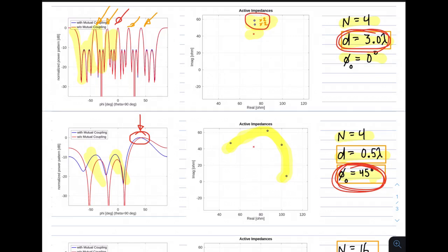Not just for this one pointing, but if you wanted to do a good impedance match for all possible pointings in the H-plane, you see now that you have a very broad range of possibilities you would have to account for. Again, this is called scan dependence. Scan dependence refers to the fact that these impedances are all moving around as a function of beam pointing.